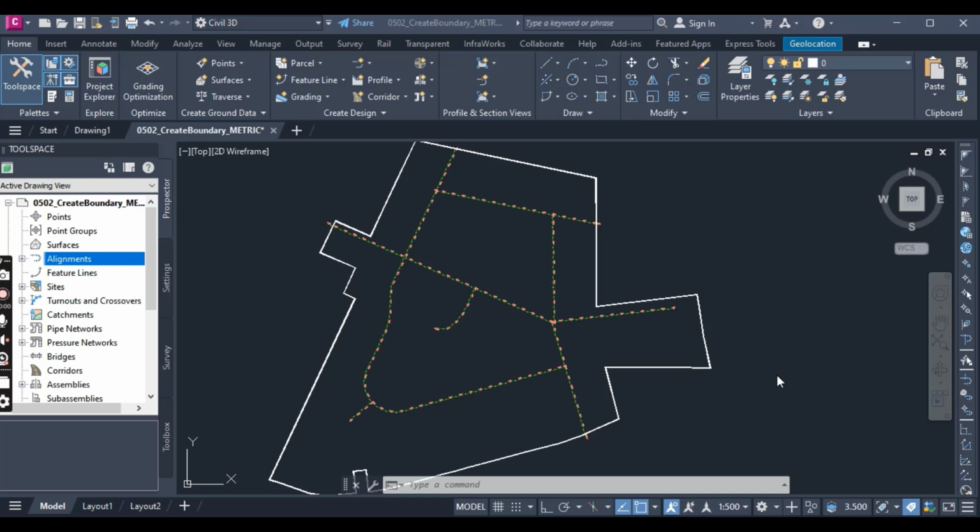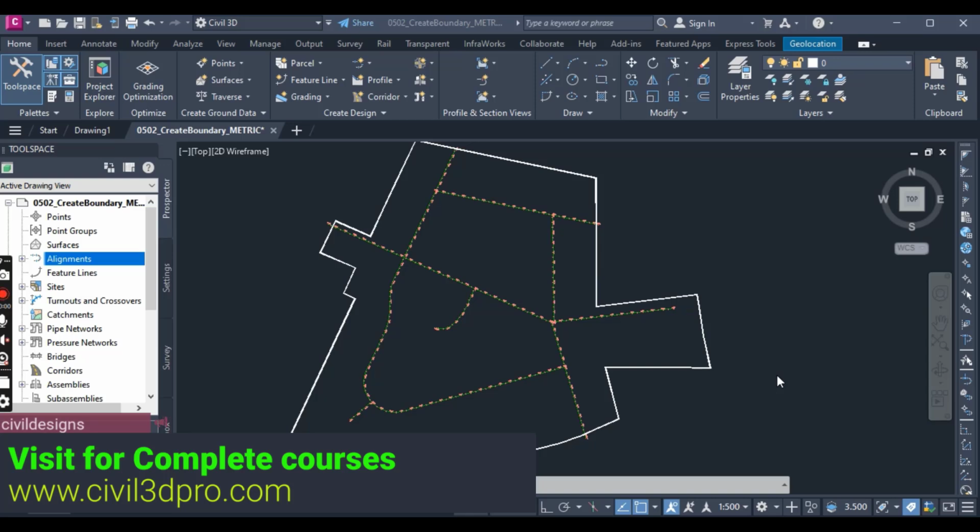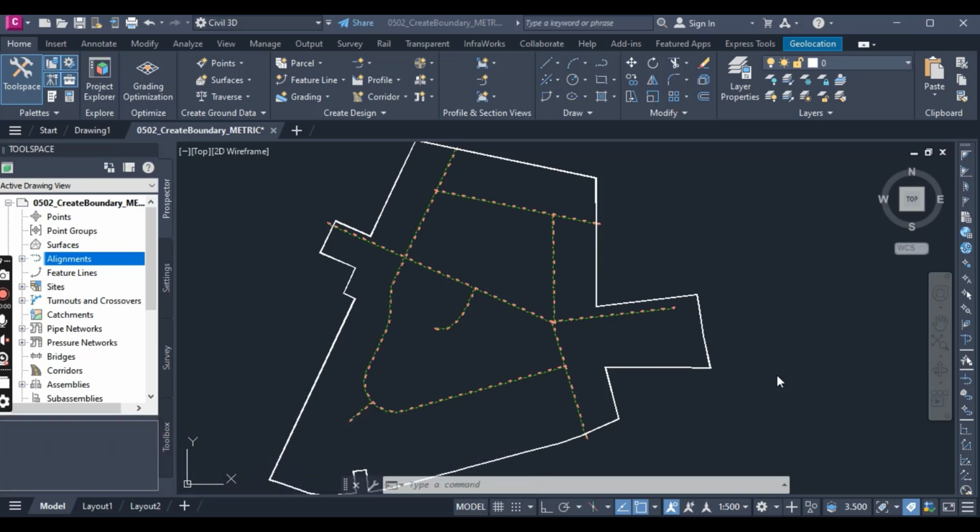in a reference drawing. In a typical workflow, it's common to encounter a boundary created by AutoCAD entities such as polylines, lines, and arcs. When we are using AutoCAD geometry to create parcels, it's important that the geometry is created carefully and that it meets certain requirements. The AutoCAD geometry must be lines, polylines, 3D polylines or polygons. So it can't include boxes, ellipses, circles or other entities.